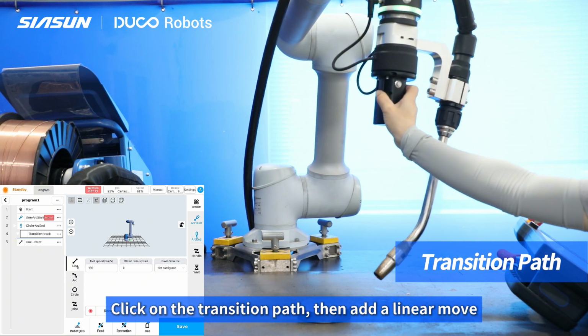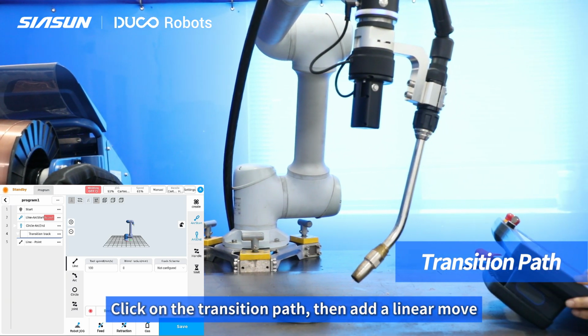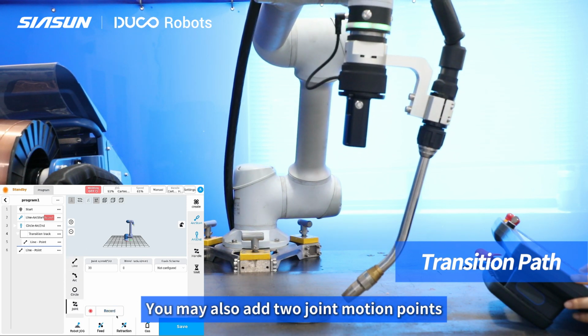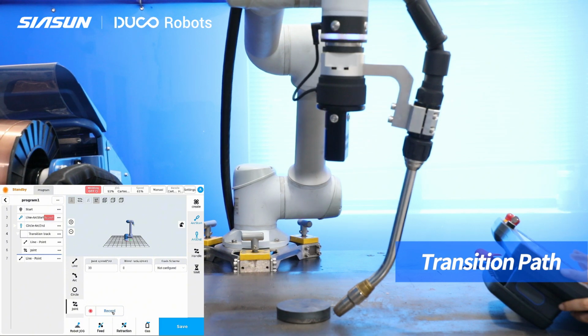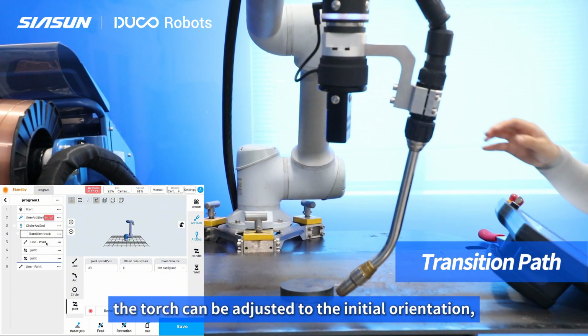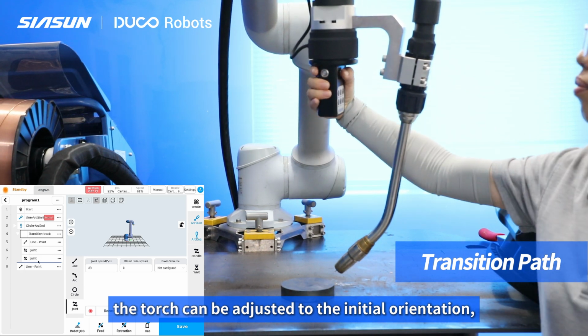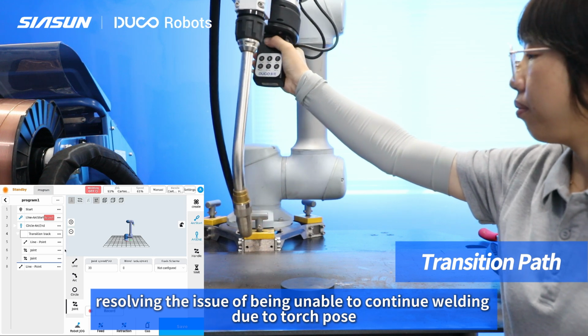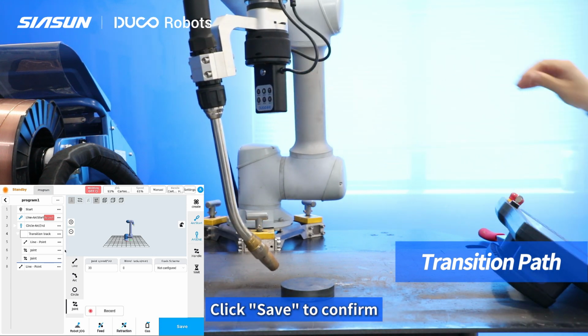Click on the transition path, then add a linear move. You may also add 2 joint motion points. Using these 2 or 3 motions, the torch can be adjusted to the initial orientation, resolving the issue of being unable to continue welding due to torch pose. Click Save to confirm.